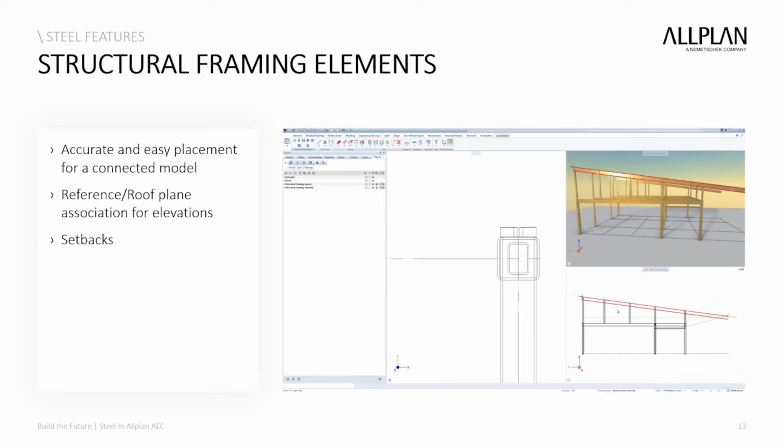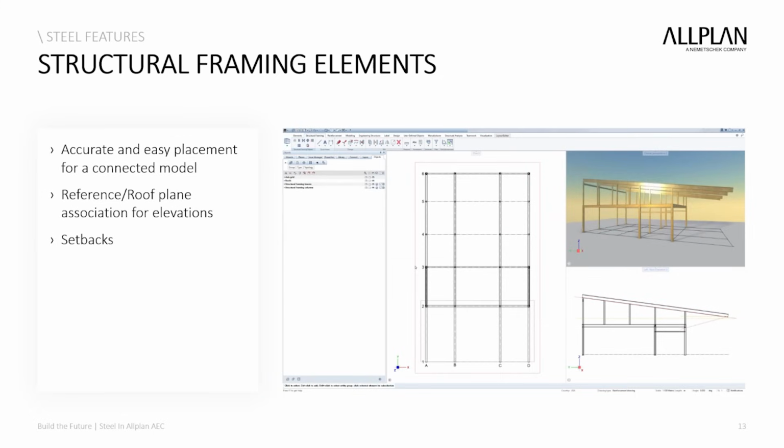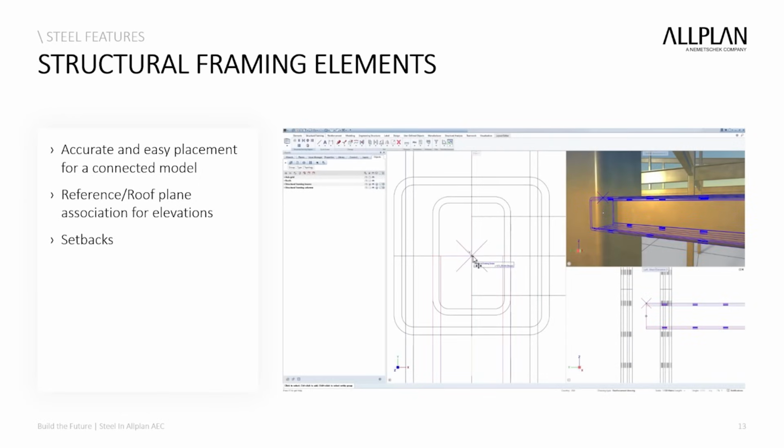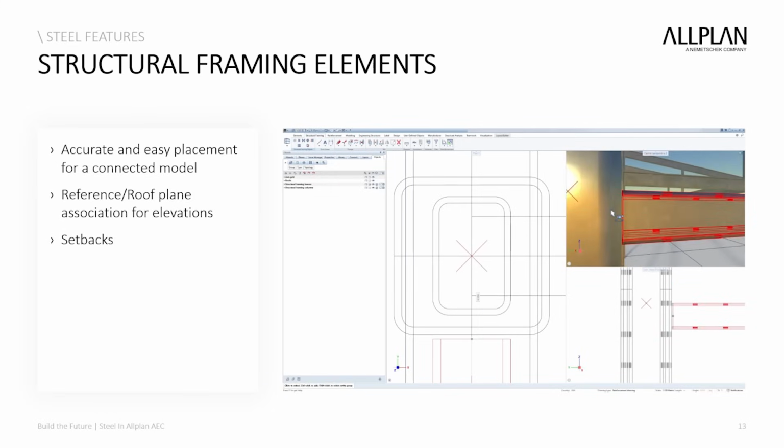We could use the bottom of steel as reference to develop the actual rafters. When modeling against reference planes, structural framing elements automatically adjust to plane modification, saving you valuable production time when changes are requested. You can use element endpoints to input the structure or numeric entry to setback elements to the faces of their support. This is unnecessary if you intend to automatically model steel connections, which is the next topic for